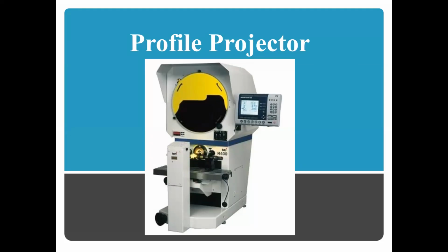Then you can measure the dimensions. The measured dimensions are in the enlarged view. If you want the actual dimensions, you have to divide by the magnification value, right? In the diagram, the large size screen is there, onto which we project the object image by using different optic principles.